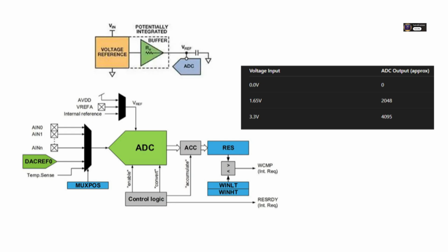While you might adjust Vref to better match your sensor's output range, which can effectively change the voltage value of each step, remember, it also changes the ADC's overall conversion range. You might gain sensitivity in one area, but lose range overall.